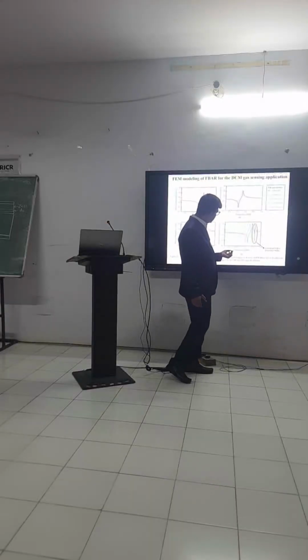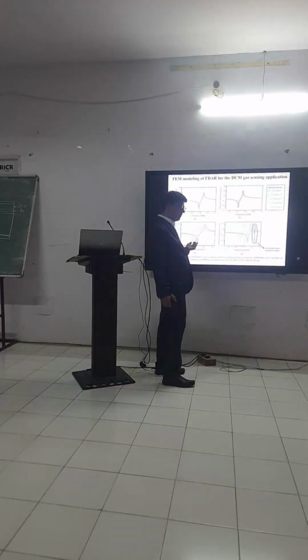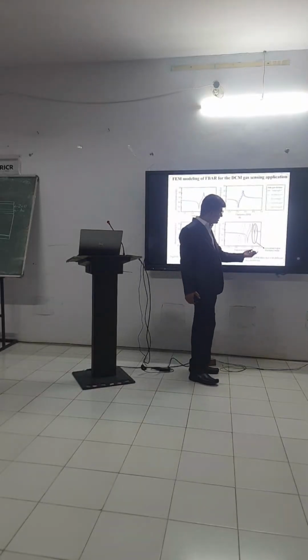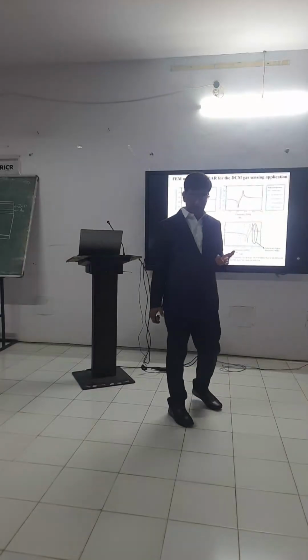Now we increase from 340 to 510 nanometer. Then you can see we have a very good shift in my frequency. Then again I increase from 510 to 680 nanometer. Then you can see here the frequency is still shifting with increasing layer thickness. But what? Extra harmonic modes are generated. These are unwanted modes and they will disturb the performance of the sensor.